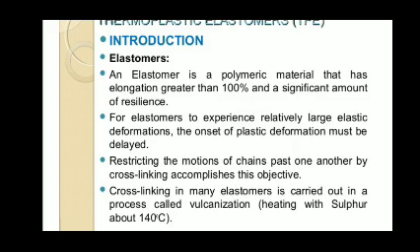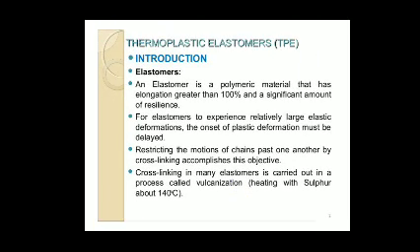In this process, sulfur is added to natural rubber or synthetic rubber to increase the strength of the rubber and modify its characteristics, with formation of a new carbon-sulfur-carbon bond. It is a very strong bond, unbreakable by applying heat and pressure. So this process is called the vulcanization process.